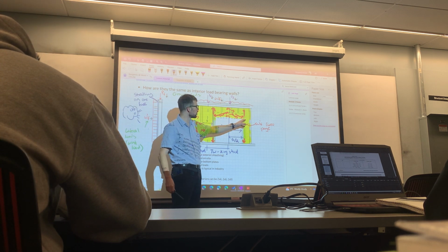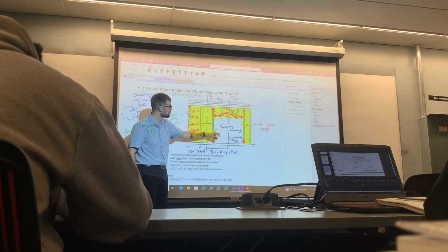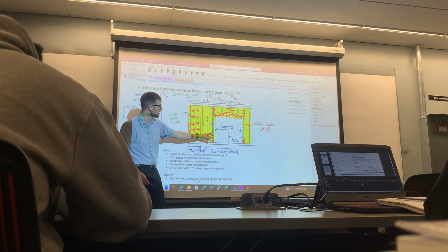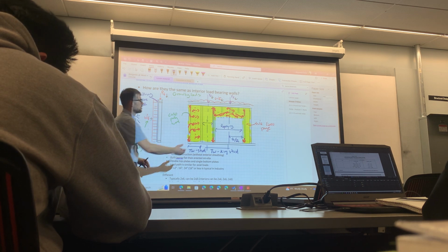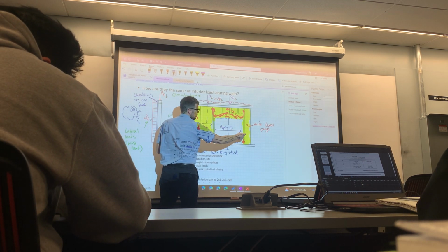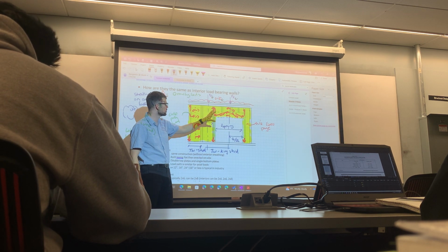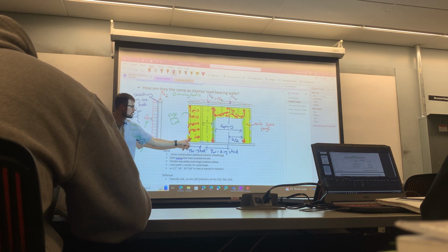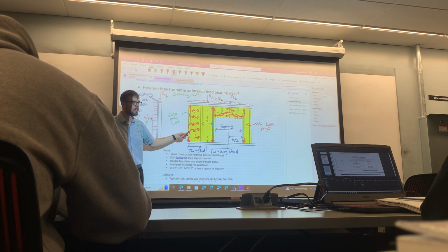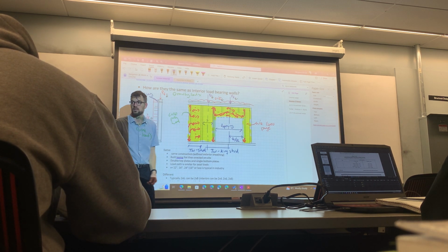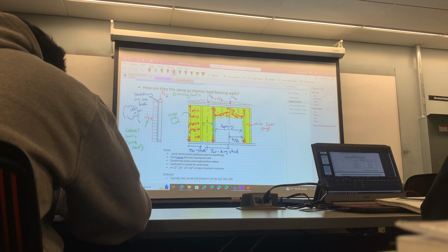There's going to be a little bit more. We know the clear span includes half of the bearing on each side, I just put the opening one. But basically the king stud needs to hold the distance between what's on the left and what's on the right. If you have double openings, this will have to hold to the next king stud there. So we distribute the load similar to the gravity loads, and then when it comes to the studs, they're distributed between the stud spacing. Studs are similar to joists, and the king studs are similar to beams. The load gets transferred to the king studs via this header and the sheathing over the opening.